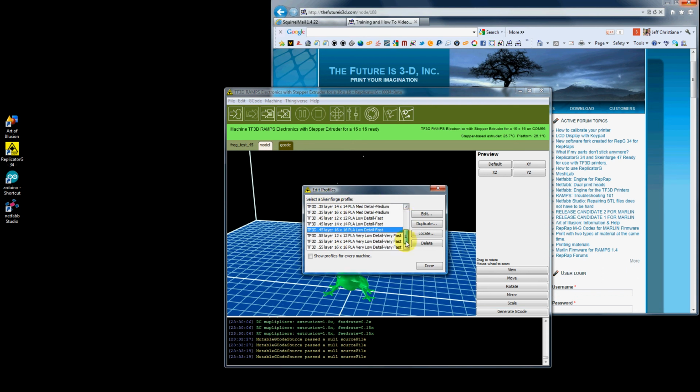These ones here, these are all the same. Basically what I've done here is I've taken layer height 0.15 and I have tweaked it to where they print out the proper speed, the proper plastic, all of that, and each tip is a little different. We're going to be standardizing on a 0.35mm tip. So what I'm going to do is go through and totally calibrate. Most of these are calibrated for a 0.4 tip, not a 0.35 or a 0.5.